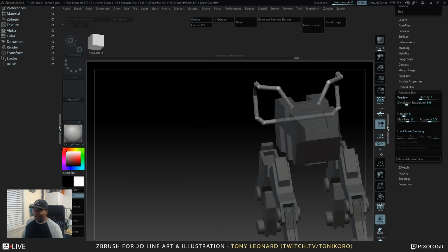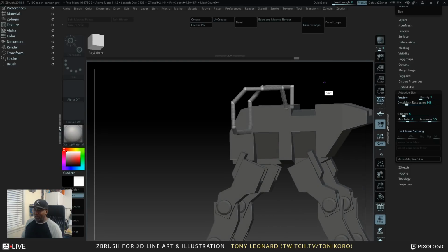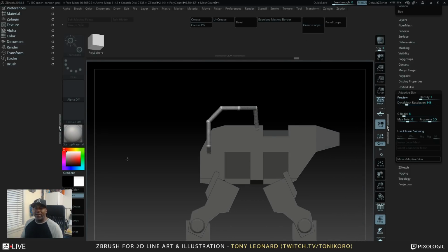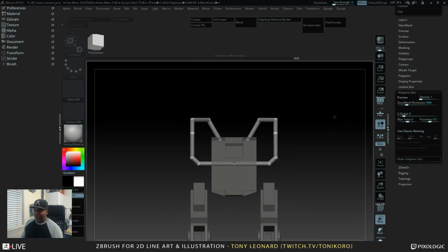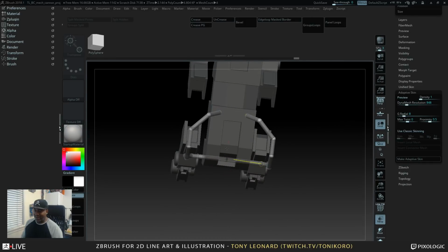So, I guess it's a way that you could figure out if you wanted to. I think in another package I would do it completely another way. I would probably use the more standard Blender way, or Maya way of doing things, so just using a curve and then maybe extruding that. You can create a curve by extruding the actual vertice. You could take one object and collapse it to a vertice, and then from that vertice you just keep extruding and bending it, and then you could change that fill to a pipe shape in Blender.